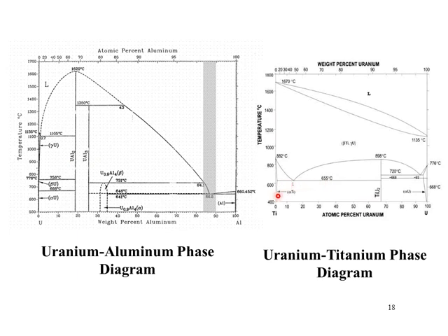And with titanium, we can form some of the alloyed species along with some intermetallic species. So again, depending upon the exact amount of material, generally alloys are better if you have a relatively low amount of material in the uranium metal. Even titanium, we said that it alloys, but at a high enough concentration, we start to form these intermetallic species.